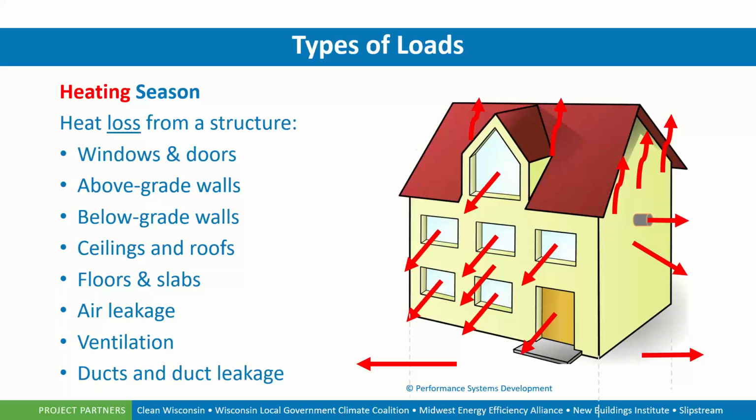The heat that we lose through our ceilings and our roofs, whether it is a flat ceiling with blown insulation or batt, or slope ceiling, or an encapsulated attic where maybe spray foam was applied to the roof deck. How are we losing the heat through that ceiling and roof? We also lose heat through our slab and any of our floors over garages, floors over ambient space or outside space, floor over an unconditioned basement. Making sure that those floors are properly insulated and sealed as well.